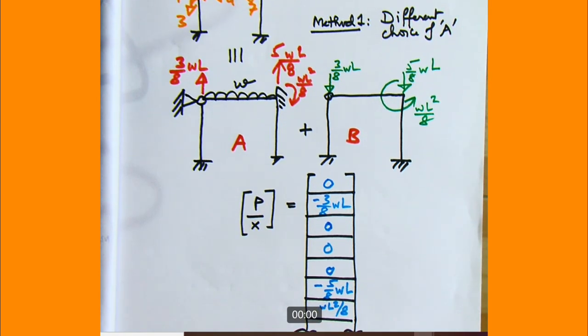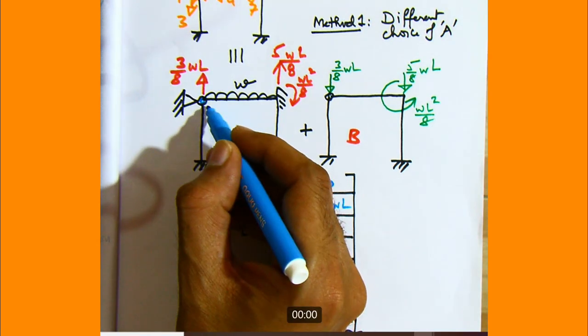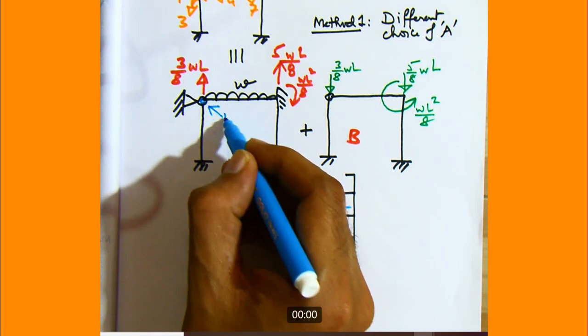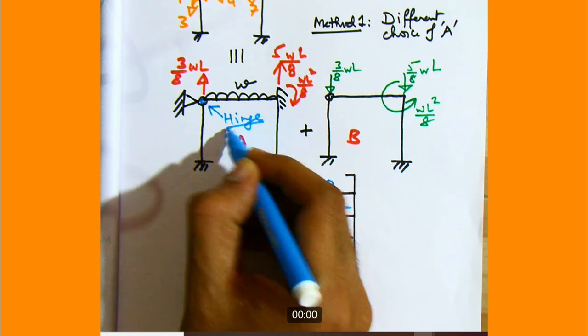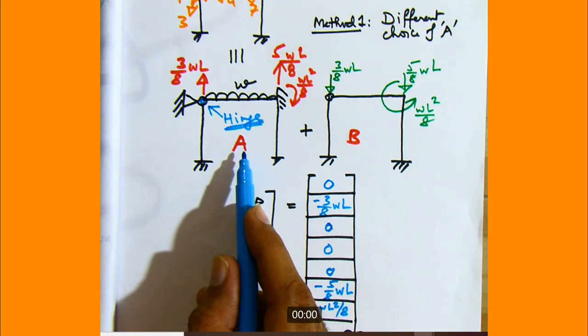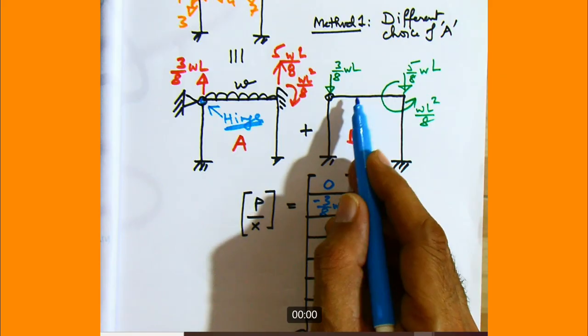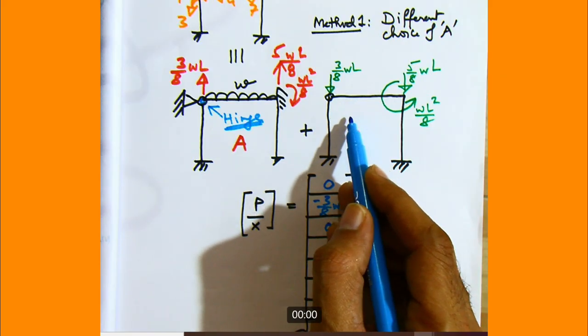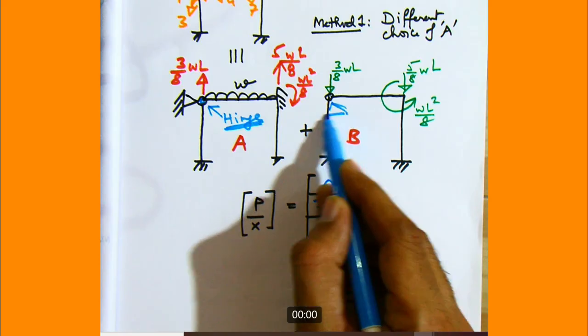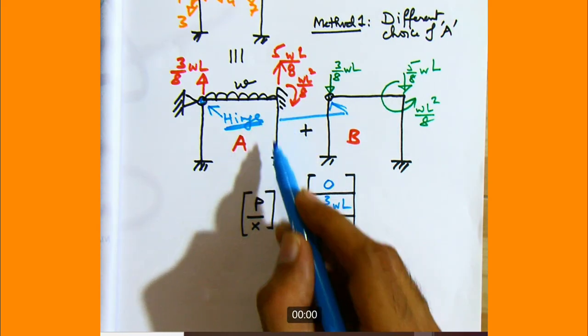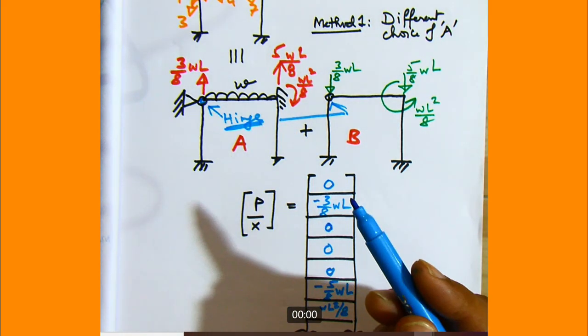So what we have done here is that we have assumed a hinge in both the structures, that in the locking condition also it's a hinge, and when we apply the equivalent opposite, that time also it is a hinge, that is structure B also, in both cases it's a hinge. So when we superimpose, hinge will remain hinge, so nothing will be added. So the final member end moment here will be 0 automatically.